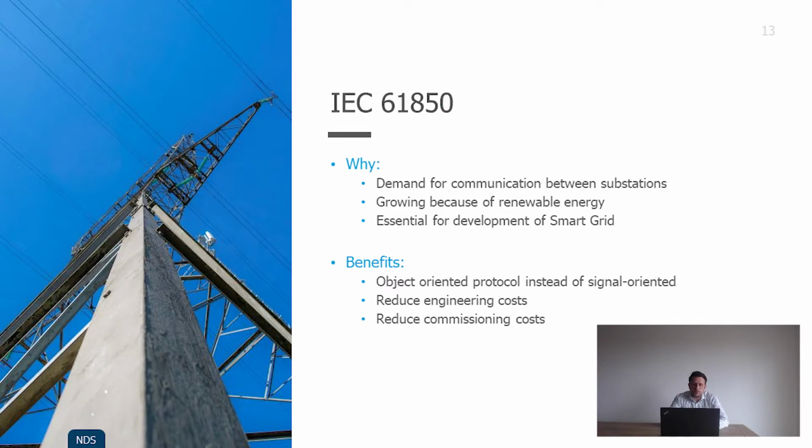It also utilizes a virtual object model of logical devices, logical nodes, and each data element is named using a descriptive string, compared to the old legacy protocols where normally it was a number representing the data. Furthermore, the standard also includes predefined object models for commonly used devices in the power industries, such as circuit breakers and switchgear, and also wind turbines.